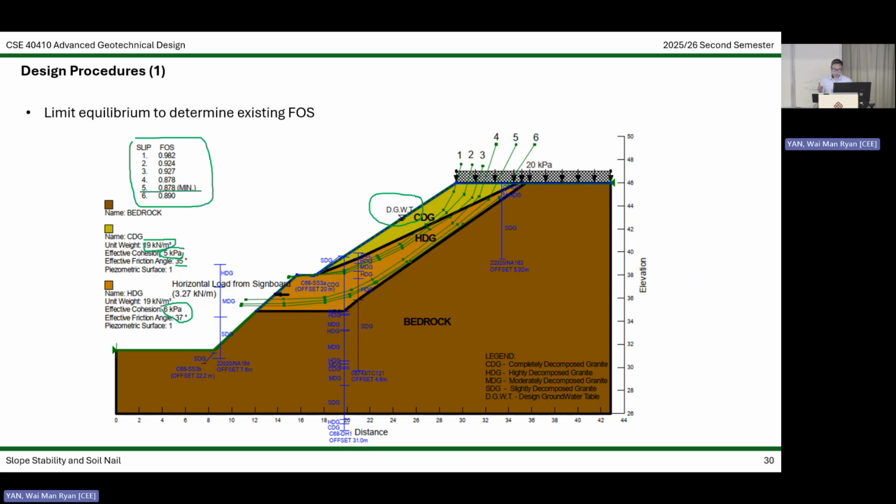If you still remember what we have done in the infinite slope analysis, water has a huge effect on FOS. If you have a parallel seepage, the FOS will actually reduce by 50%. So here, if this is dry, maybe the slope has a FOS of 1.4, 1.5. But because of this seepage, because of the high water table, here we don't actually model seepage. This is the limitation of slope W. We simply consider the hydrostatic water pressure, but that's okay. It's on the safe side, as I mentioned last week. Anyway, we got a FOS smaller than what we need.